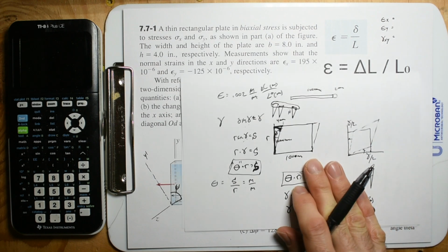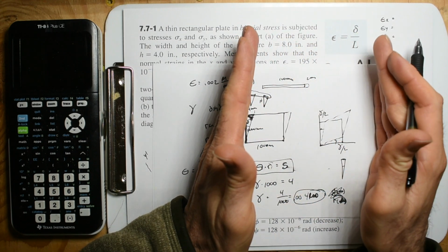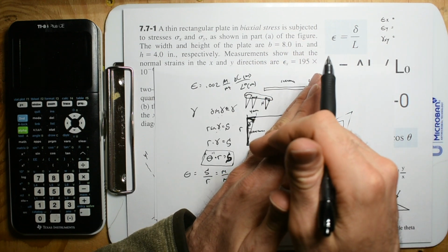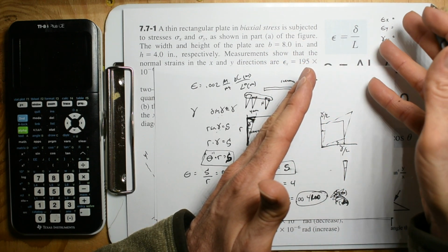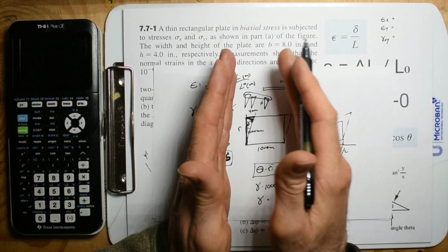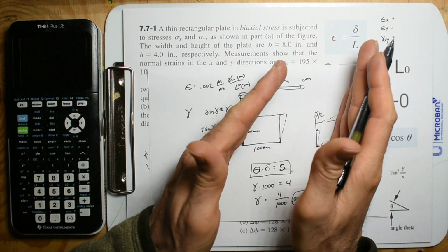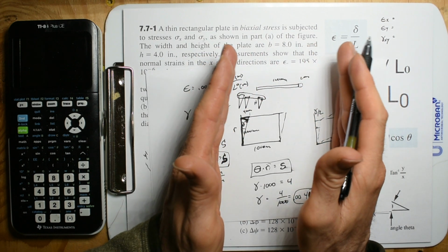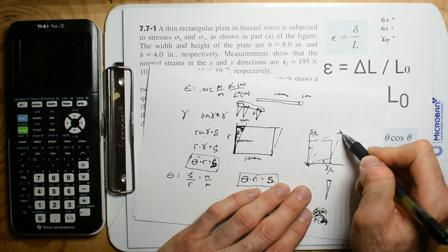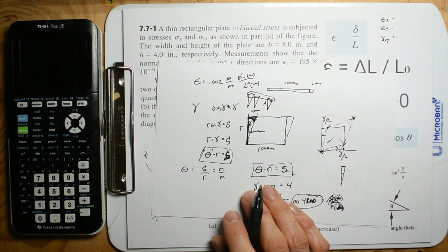All right, so I just showed you there. That is very important. It shows you that this angle that forms is way different than just shifting in the normal shear. So this angle that forms is called shear strain. Strain is just a word for deformation. I just like to think changes in length. Obviously, normal strain is a very obvious change in length in the x or the y. Where shear strain, nothing really has to definitely change in length per se, but for sure from there to there, this length gets longer, this length gets shorter. And so you can still think of it as a change in length as well.